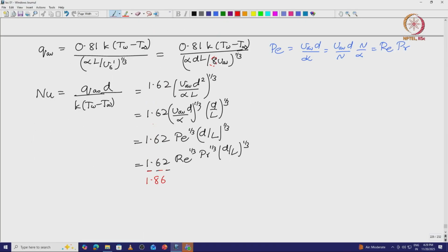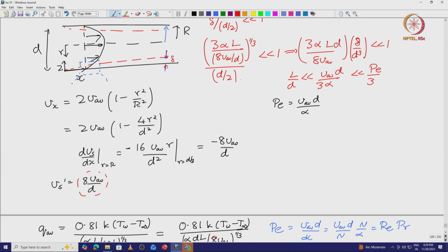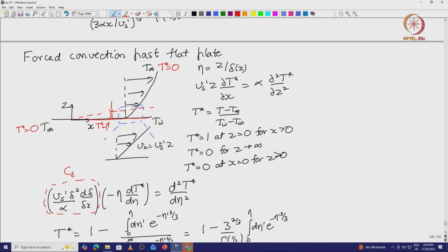In the last lecture, we were looking at the boundary layer analysis of transport from a heated surface under forced convection, where convective effects are dominant compared to diffusive effects. Even when convection is dominant compared to diffusion, there is still a thin layer close to the surface where diffusion is important, because if you neglect diffusion altogether, then the equation just reduces to the velocity dotted with the gradient of temperature is equal to 0.